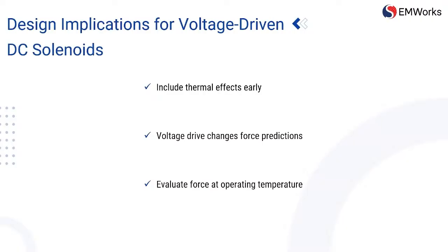Thermal effects must be included from the beginning of coil design. Voltage drive fundamentally alters force predictions compared to current-driven assumptions. Force should always be evaluated at operating temperature rather than at cold startup conditions. Adopting this approach significantly reduces the risk of late-stage redesign.